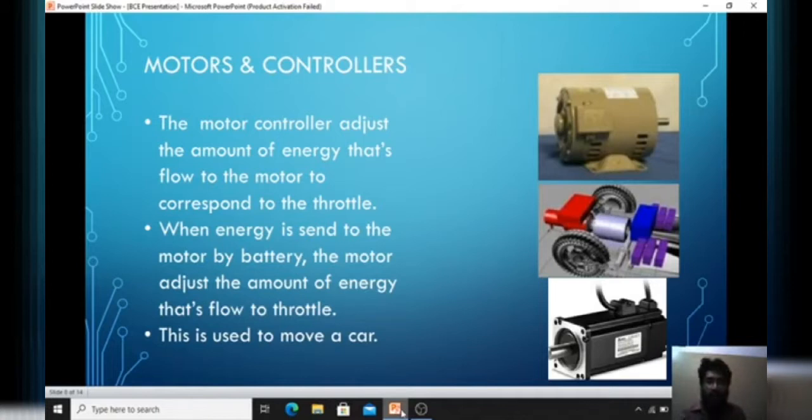Here what happened: first, energy came into the solar panels. Solar panels convert the solar array energy into electrical energy. Then it is sent to the power tracker. The power tracker then allocates energy to different parts of the car, and then the batteries will do work in the future, when there is no sun or in rainy, cloudy weather. And then, either in rainy days or at the end of the day, the energy which we achieve from the solar array goes to the motors and controllers.